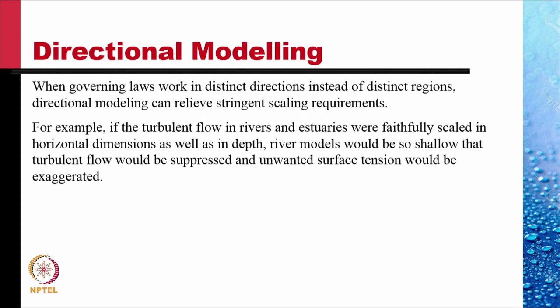Directional modeling. When governing laws work in distinct directions instead of distinct regions, directional modeling can relieve stringent scaling requirements. We have done this earlier in a different context. For example, if the turbulent flow in rivers and estuaries were faithfully scaled in the horizontal direction as well as in depth, river models would be so shallow that the turbulent flow would be suppressed. And in addition, unwanted surface tension would be exaggerated.